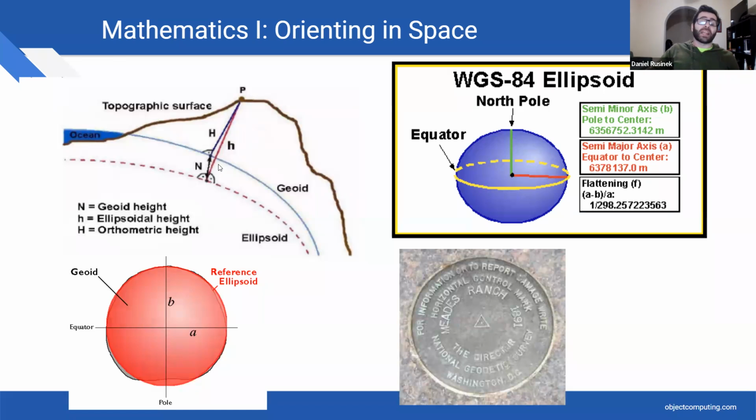So in the case of what we're working on right now at OCI, we actually have to try to transform to this local elevation. So we kind of have to take some measurements and there's some APIs, there's a USGS API, there's also the Google Elevation API, that you can use to then transform to that actual local elevation. Because for train companies, for a lot of these freight companies, knowing how high vegetation or something else is above sea level isn't very useful to them. So that's something that you need to take into account. Thank you, Marty.